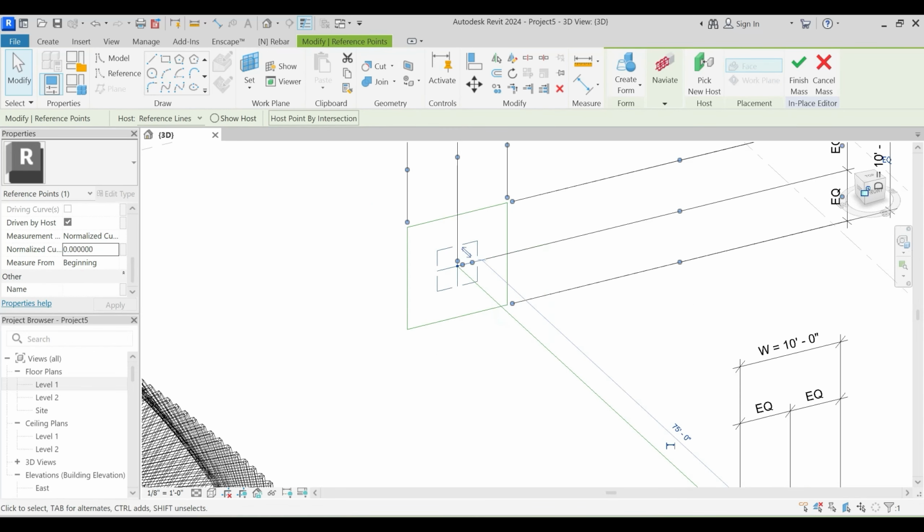Okay, and last but not least, this particular surface, press Tab a couple of times. Yes, and divide surface. Just say that 25, 30, 25, and 60. Okay, and you see that we have achieved that particular thing, wherein this point, these particular lines are matching. Okay, so now what we need to do next is define a pattern based